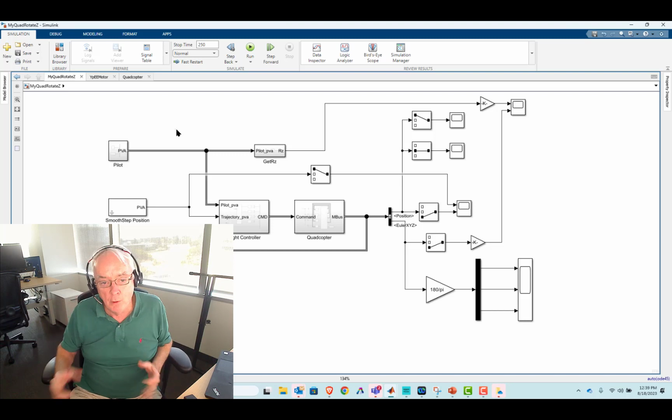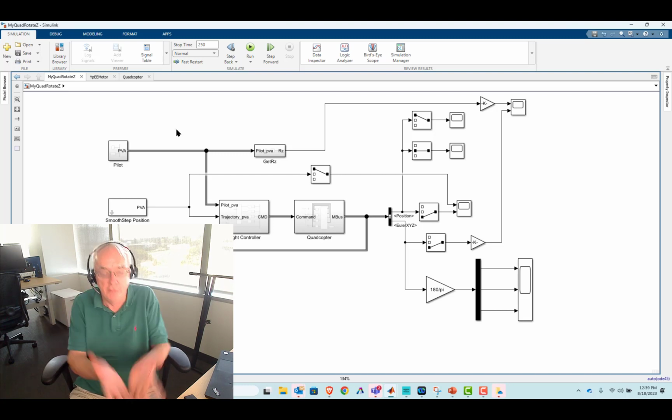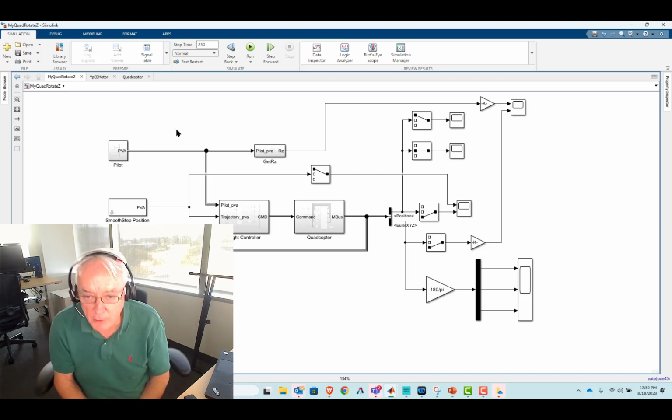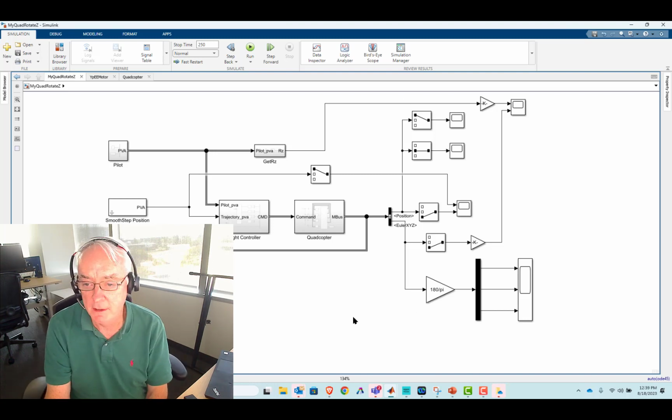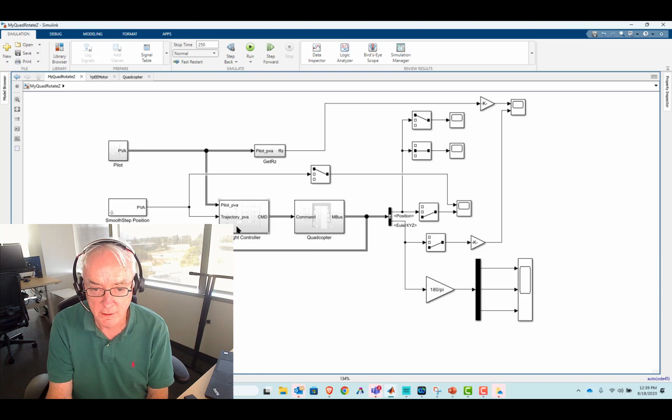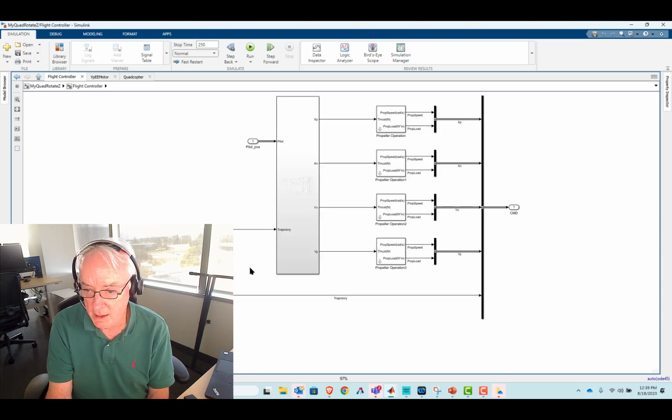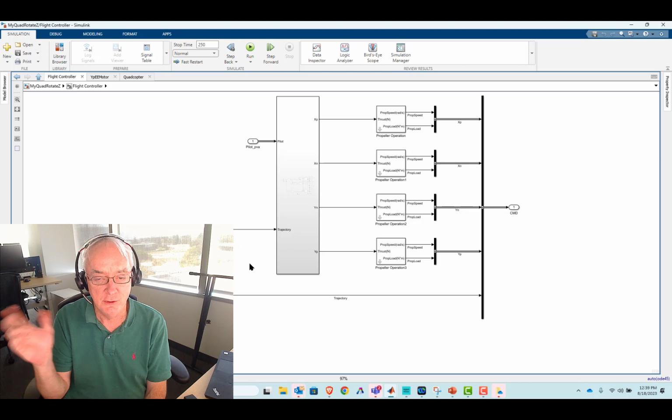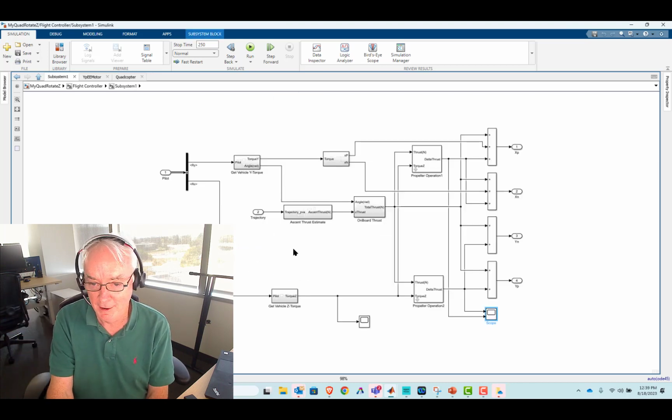Why pitch and roll are almost, by definition, certainly by the design, decoupled completely from the thrust control, right? They contribute zero to the thrust that's going to ascend the vehicle. So, anyways, it's not quite so easy with yaw, right? And it's that aerodynamic additional torque, which at this point is kind of preventing me from doing much better.